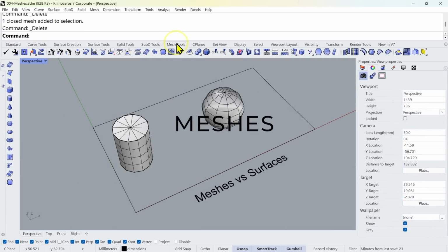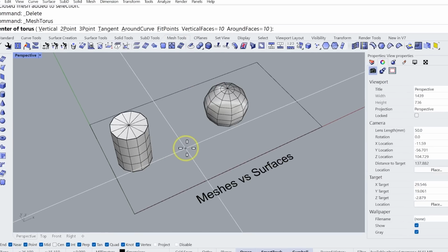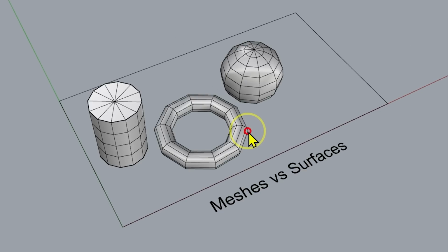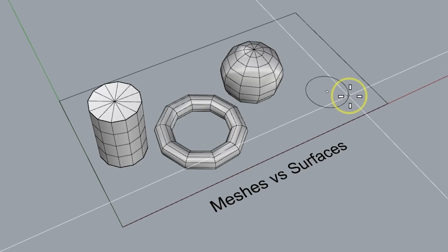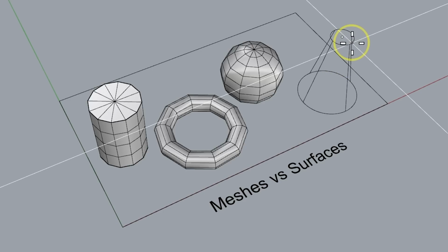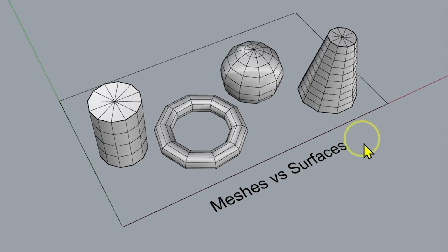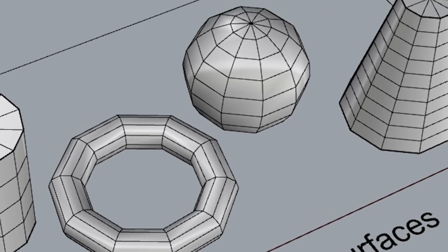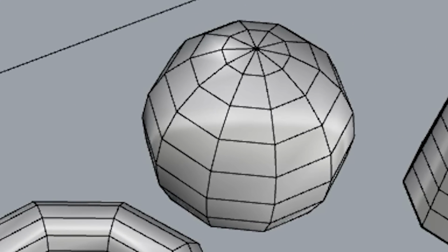The last important object, which comes in very handy during complex modeling or prototyping, is the polygon mesh. In Rhino, polygon meshes are another object type used to create and edit 3D models. Unlike surfaces, polygon meshes are made up of points which are also called vertices. These vertices are connected by straight lines to form polygons, usually with 3 or 4 sides.